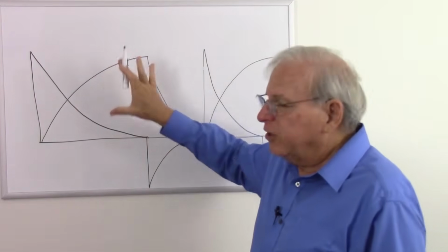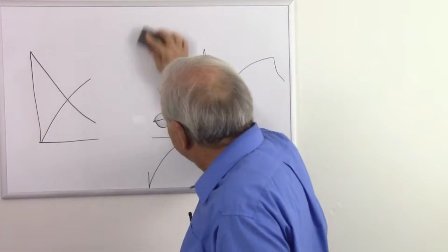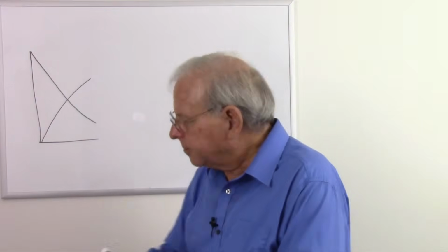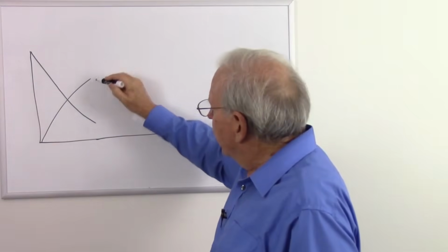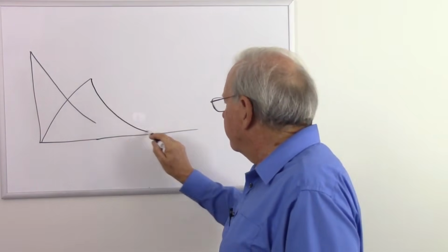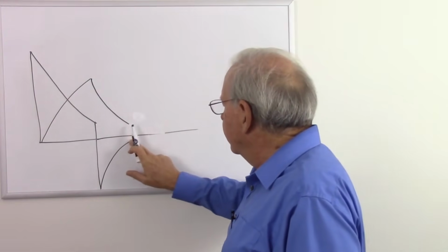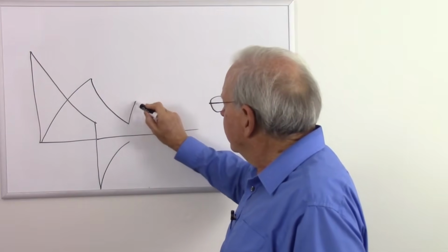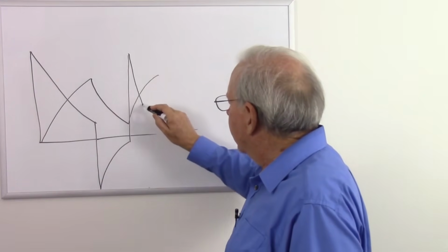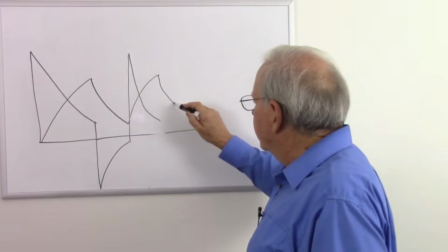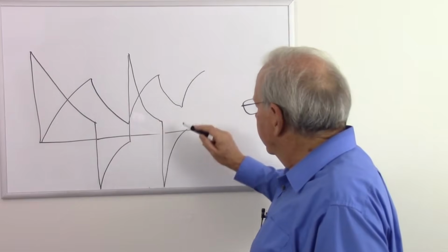So let's flip the switches even faster at a higher rate, at a higher frequency, and see what happens. So let's erase that to there. Right at this moment here, I flip the switch and let it discharge. That jumps down to negative, and I'm not going to let it discharge all the way. Now I'm going to start the charge again, and that's going to jump up to a high current and then drop back down. And then I'm going to start discharging it. Then I'm going to flip the switch again, and we're going to keep seeing this cycle.